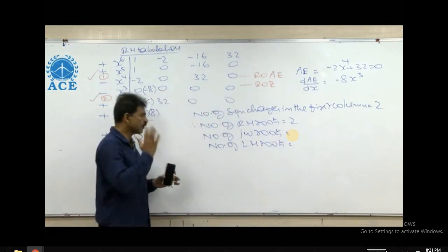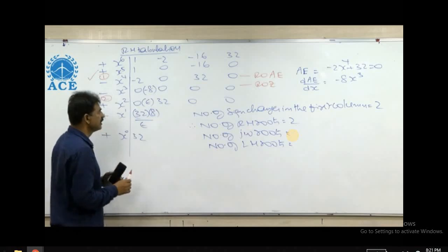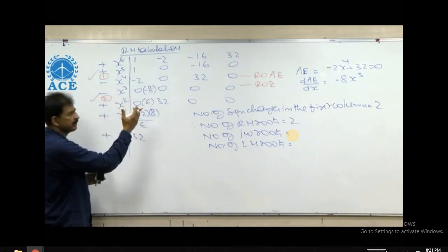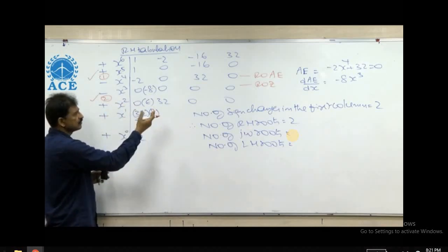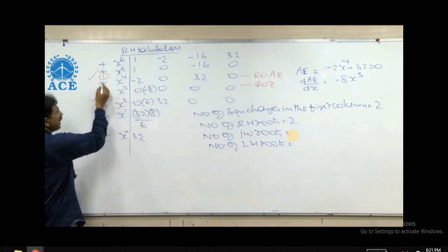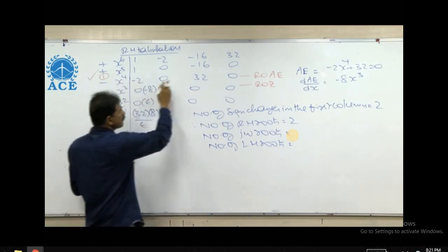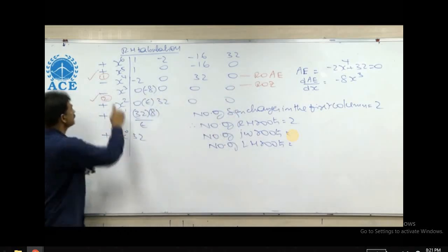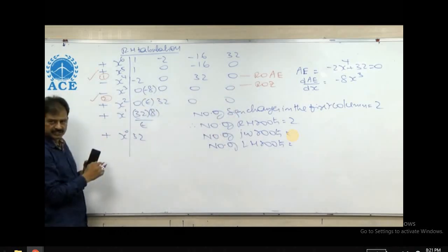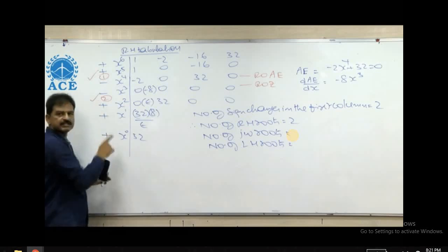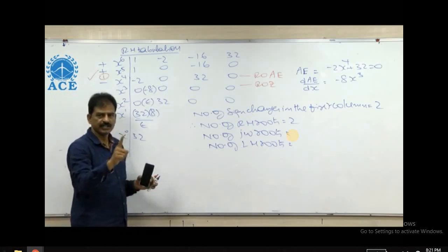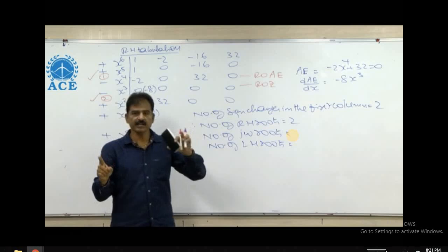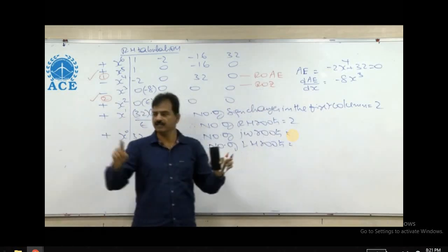To find the roots on the imaginary axis, this is a special case problem, the entire row becoming 0. So, this s power 4 row is the row of the auxiliary equation. Below the auxiliary equation, we have to see the sign changes. Below the auxiliary equation, there is one sign change, which implies one right-hand root of the auxiliary equation, therefore one left-hand.